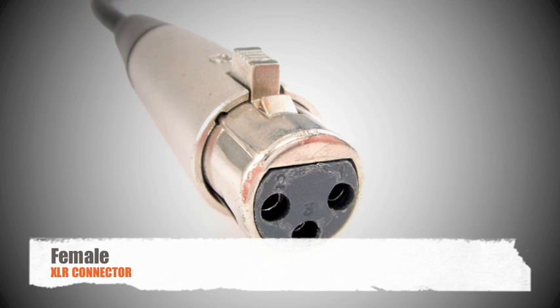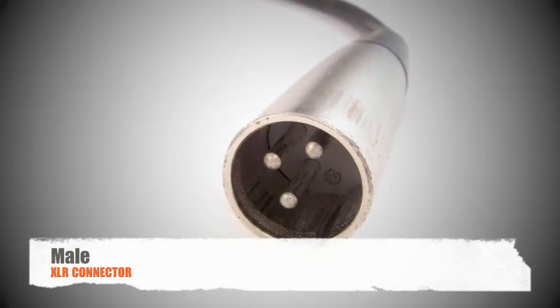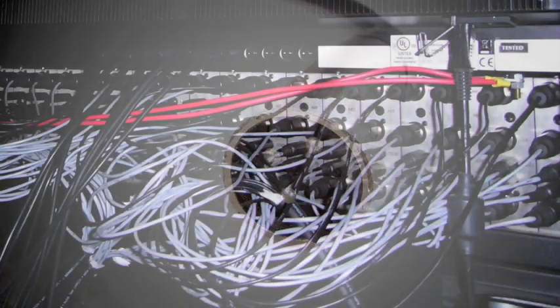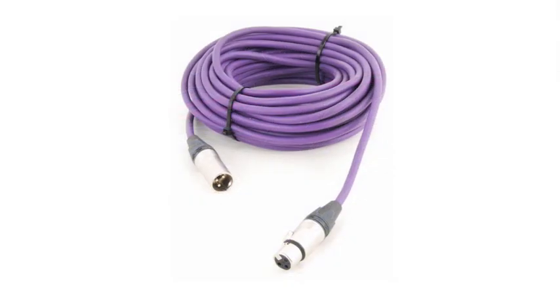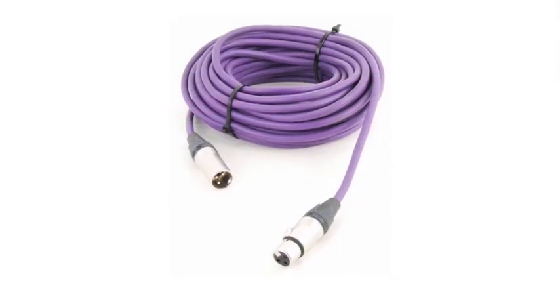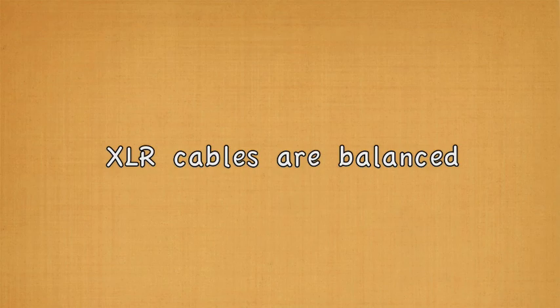XLR, or more specifically XLR3 connectors, are mainly used for professional audio. They are more often used for connecting microphones or line-level signals between digital converters and outboard units. XLR cables usually come with a female and male connector. XLR cables are balanced.